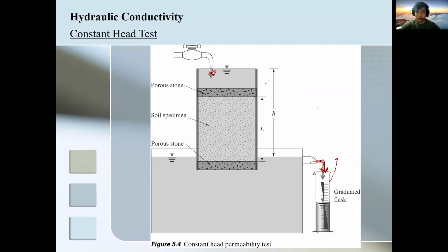So if you're going to look at the different parameters presented in the diagram, notice that this one is L, right? It's vertical. So again, as I have mentioned earlier, your length should be parallel to the direction of the flow. Since the direction of the flow is downwards, your measurement of your soil should also be in this particular axis, which is the y-axis.